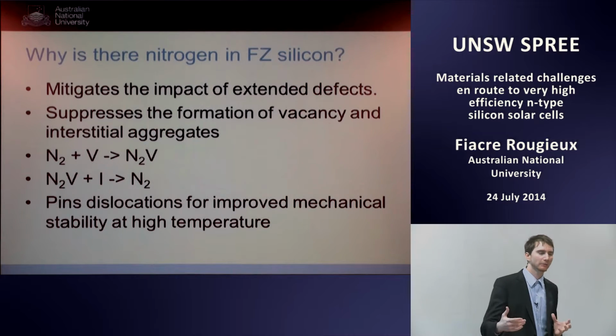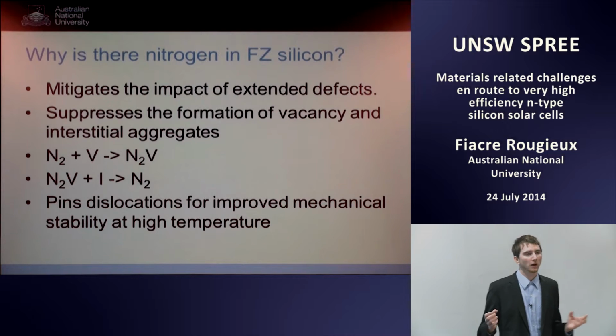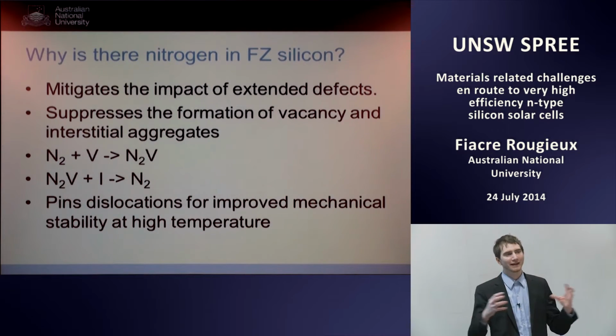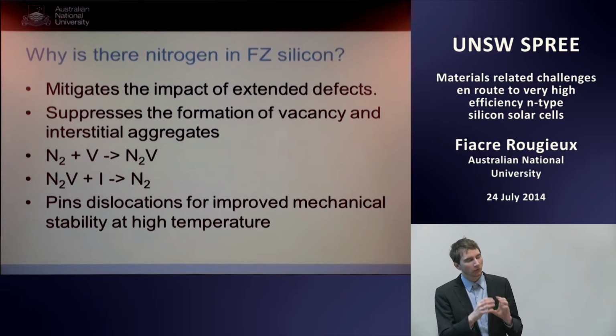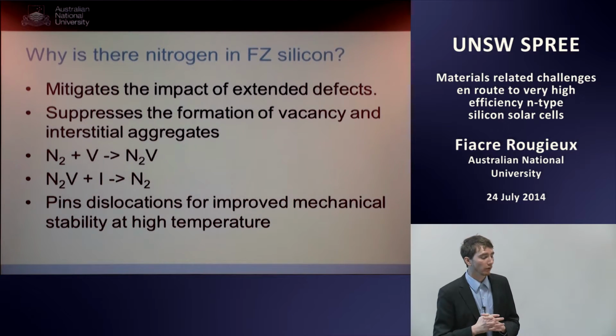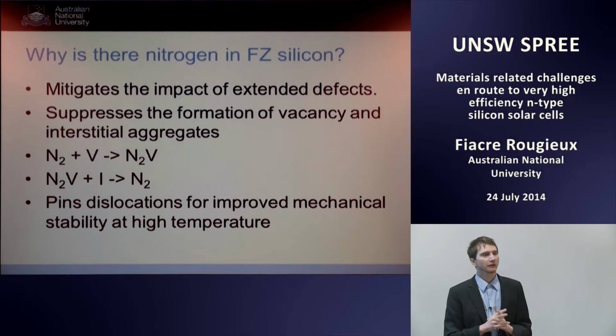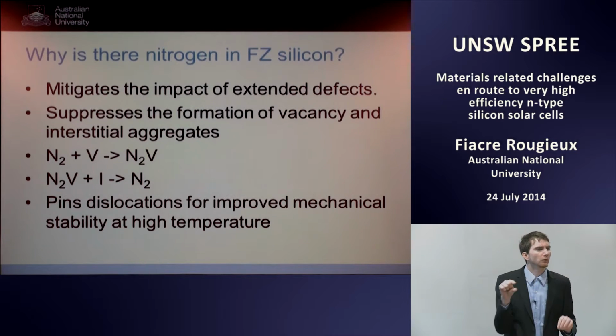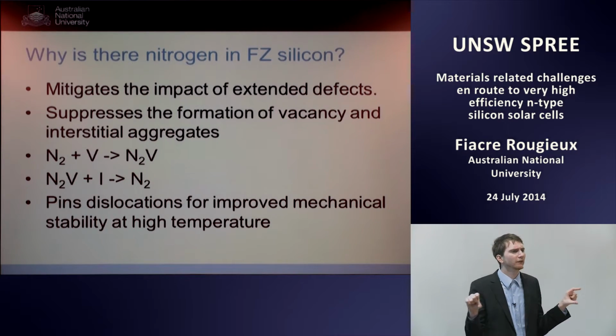So they really help in the IC industry because they stop the accumulation or the aggregation of intrinsic point defects. They really help avoid those structural or extended defects, especially near the surface. We don't want extended defects at the surface in the IC industry.